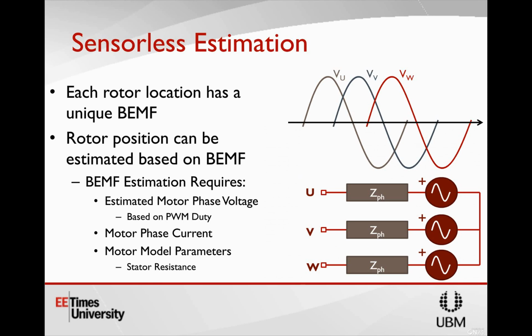This is Cheng. I can add maybe 2 more cents on top of that. Like Adam mentioned, the startup is more about when the loop will be closed, right? When the position loop will be closed. When there is a Hall sensor output, we know the position at the very beginning, so we can close the position loop immediately. While in sensorless, like Adam mentioned, at low speed, less than 10% of full speed, it's roughly open loop. The loop will be closed at a higher speed. That's it. Okay, thank you.